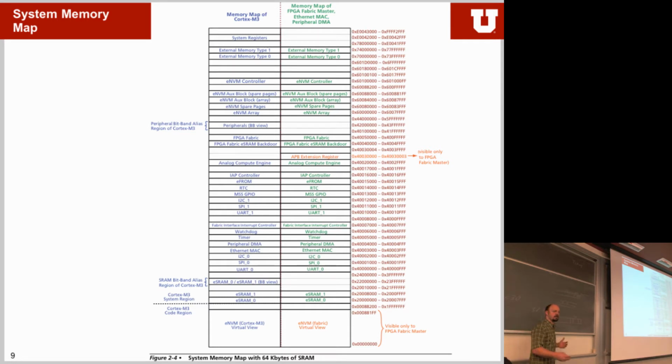Well, the first thing is you read this register out, get the status of all the different bits. Then in code, you flip this particular bit and write it back into that register. Made sense? So you read the status first, flip the bit of that status, and write it back. Then you know that these bits have not changed.